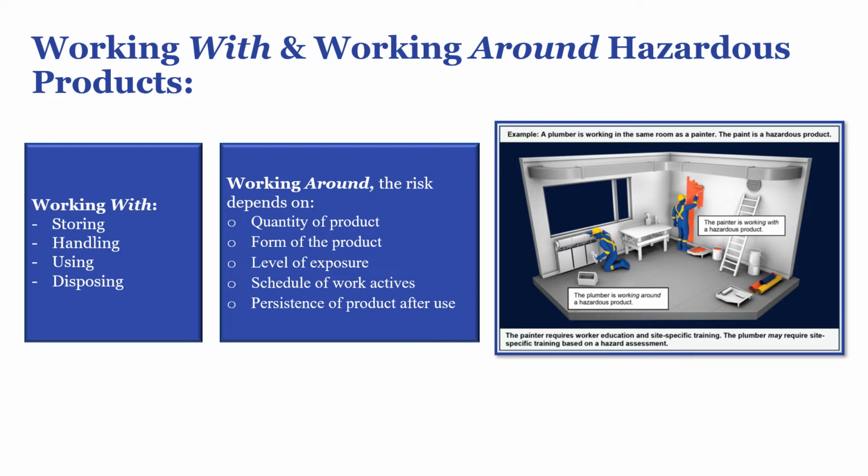For example, a masonry trade spraying brick cleaning solvent on the exterior of a building while we are working on the landscaping. This would be classified as working around the hazardous product, and depending on the following conditions identified from the hazard assessment, we might require training on the cleaning solvent: the quantity of the product, the form of the product, the level of exposure, the schedule of work activities, and the persistence of product after use.